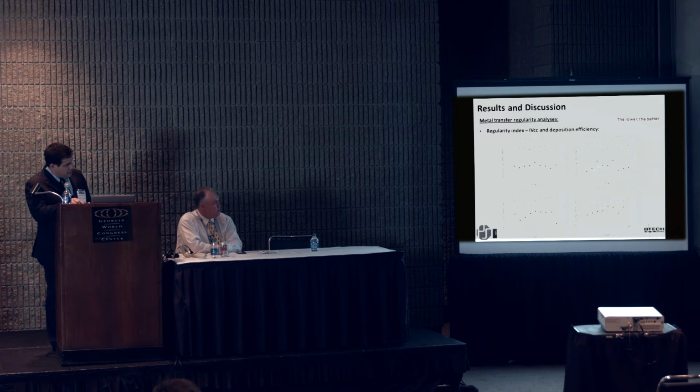But the idea is that for austenitic wire we have very good weldability. Over the voltage range, we can reach sound welding independent of the specific voltage, and in all the voltage range we reach good values.